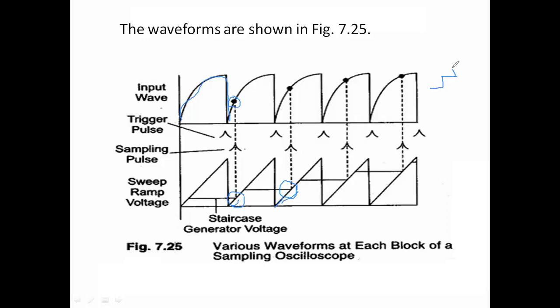It will produce the next staircase voltage, like a step voltage. So it will have a constant value at that particular level of the voltage. And in the next coming sawtooth waveform or linear ramp signal, again this ramp signal will be generated, and the third staircase signal and the ramp signal will be compared.